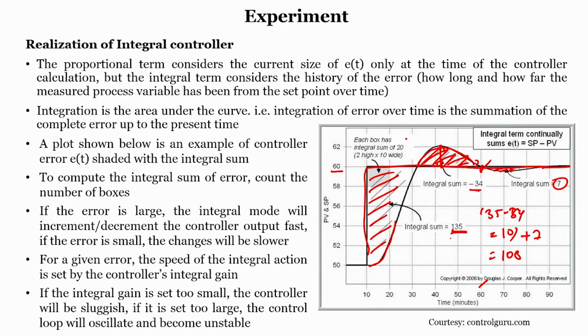So since we are using an integrated system, the complexity of the system is also increasing, but how do we design using an op amp? One thing we have to understand is that using op amps, we can do any kind of operation. Integration we can do, differentiation we can do. If you recall, the way of doing integration is simply by using a resistor and a capacitor, which does an integration operation. And a PI controller is a combination of integration as well as proportional. We have to take an adder which adds the proportional controller and the integral controller. The addition of these two is nothing but my PI controller.